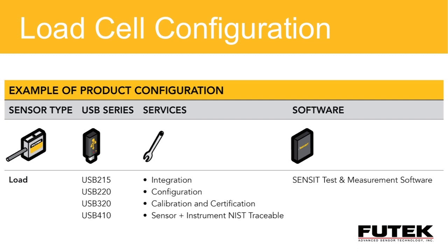Although we have focused on one specific load cell today, our LSB 200, as I've indicated earlier in the presentation, any of our strain gauge solutions, or for that matter, any strain gauge solution and other solutions will work with our USB devices. Our USB devices will support millivolt, voltage, current, and also pulsed inputs. So our devices will cover just about any traditional sensor that we'll find in the automation realm.